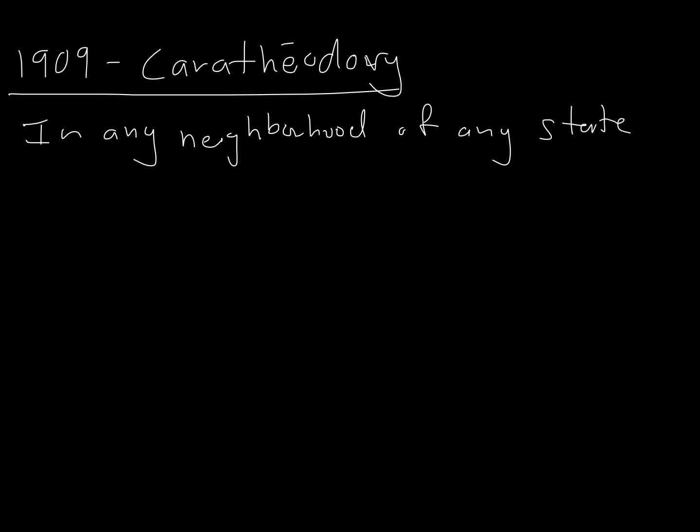A state of matter is like a particular combination of temperature, pressure, and phase. So the state of the air in this room is like 20 degrees C, 1 atmosphere, and it's a gas phase. That's a state. If I wanted to take a volume of that and transition to a different state, I would either change its phase, change its temperature, or change its pressure. So a state is the collection of variables that describe everything you need to know about that system. That's what we mean by states. We use that term quite a lot.